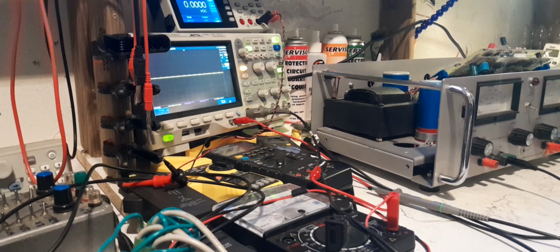If I, how do I explain it? Go up to a ridiculous figure like 47 mic, which being fed through a 1.8k dropper resistor is going to create a bit of a time constant on power up that I don't want there. Especially when there's only 10 volts available to it.